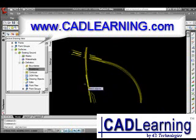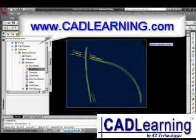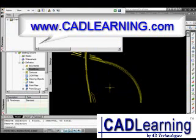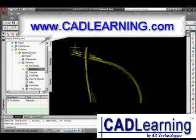I'm going to select them by window and select all the break lines, except I'm going to type R to remove the break line representing the stream bed. That will be a separate break line. Press Enter. Now we have one set of break lines for roadways. We'll repeat the process for stream bed.